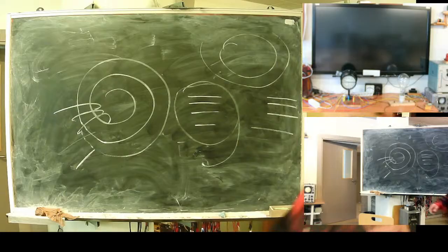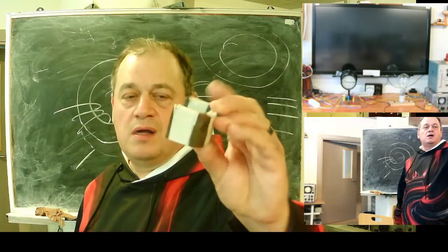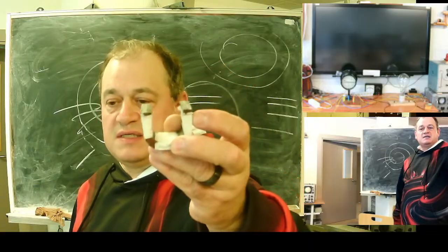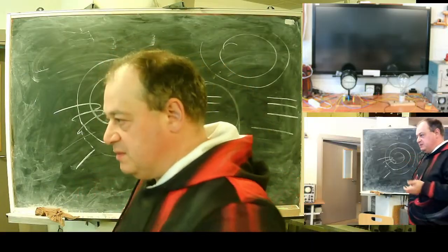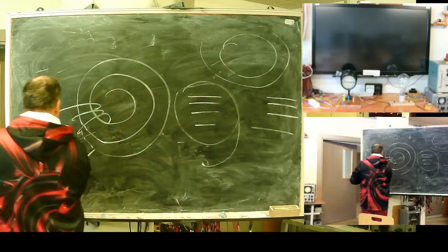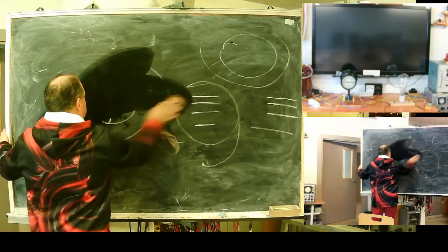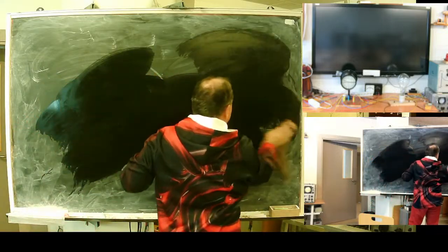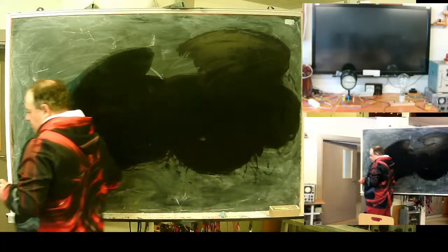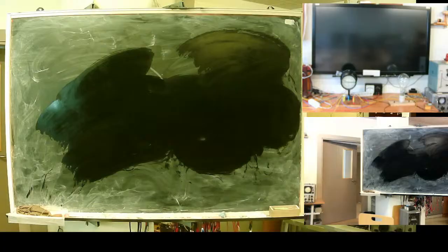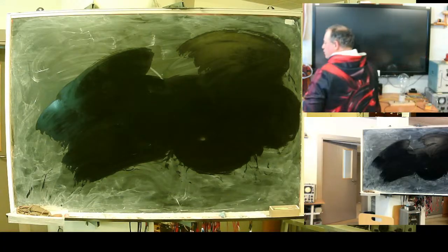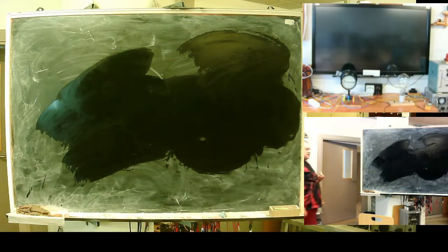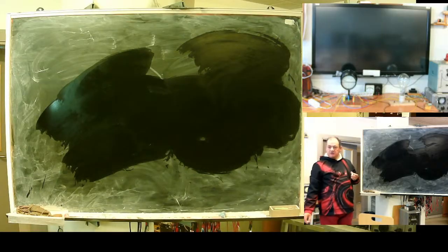Piece of transformer core, it was wound from the steel ribbon, then cut and polished. Not so good as non-interrupted, but one of the ways to fight for linearity. Energy efficiency is not a problem here. The problem here is precision, transformer precision.